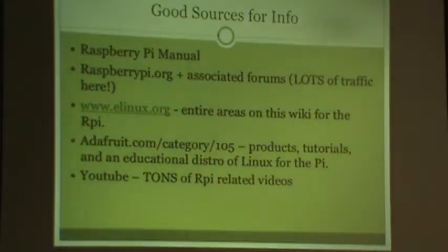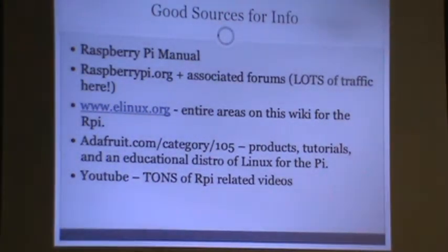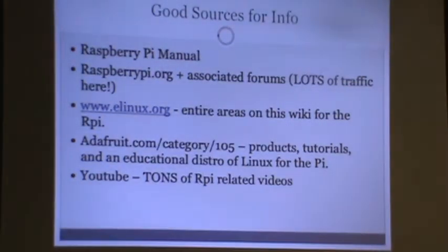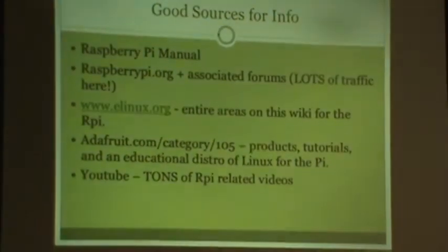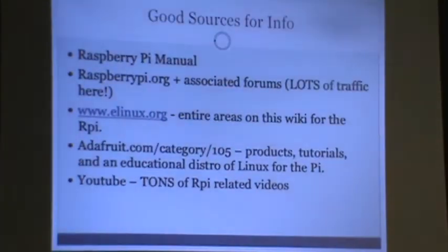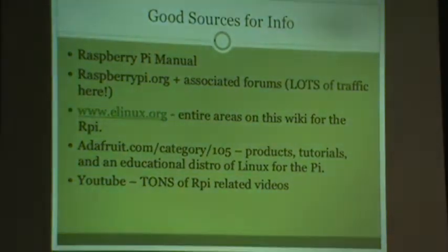Obviously, you're going to need an SD card from these guys. I recommend using Class 6. Like I said, you can use a Class 10. They've gotten better about those. The thing is, Class 10 is designed for newer digital cameras, which typically write single large files at a time.